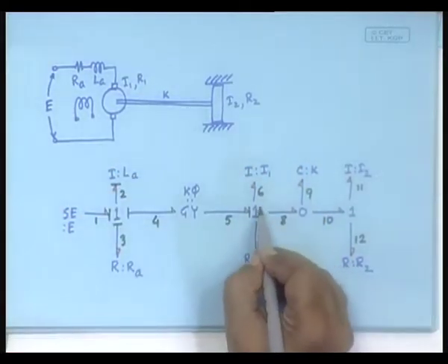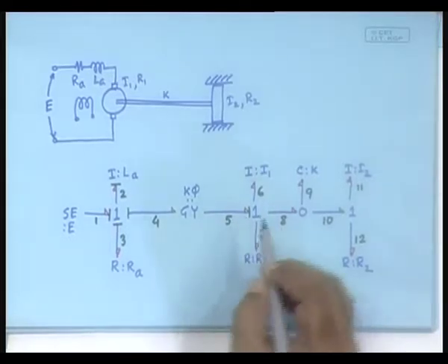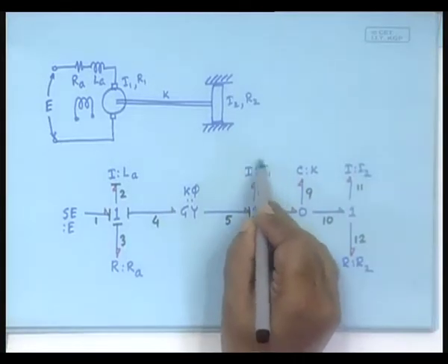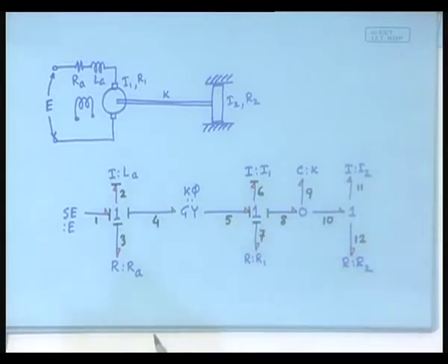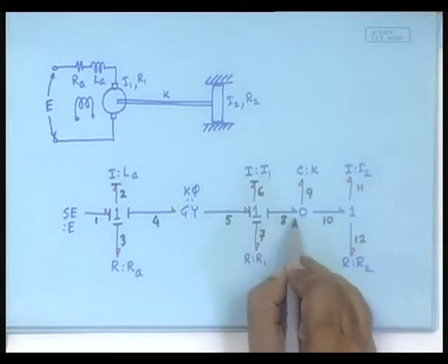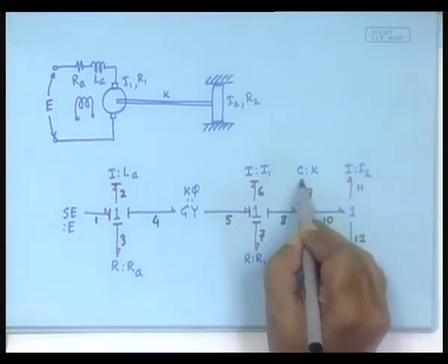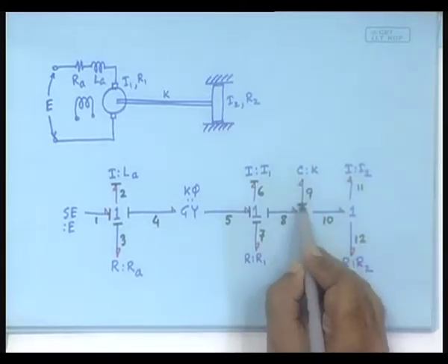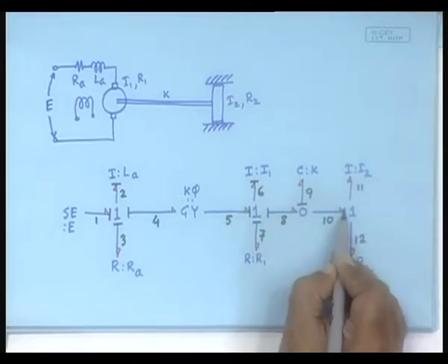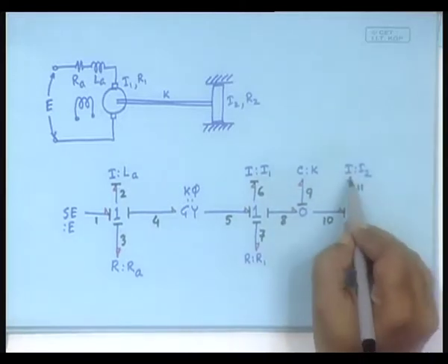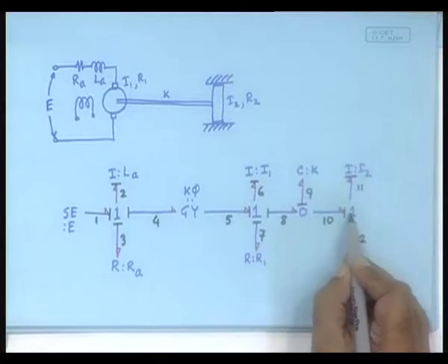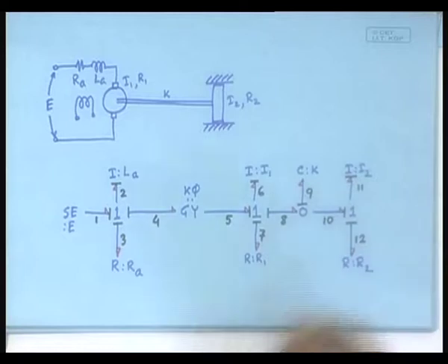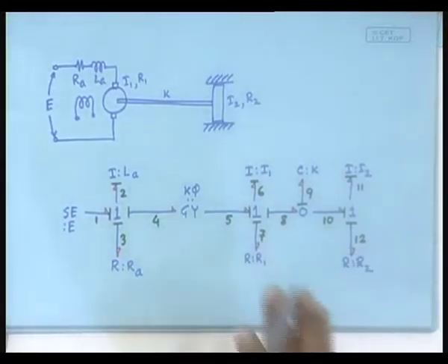So, effort goes out. Now, this one is not yet completely causal, because this is not a strong bond. So, we have to put the integral causality in this storage element, which is like this. The moment you do this, it has already obtained the flow information and must take out the flow information in the other bonds, which is right. Next you come here, this is not yet causal, so let us put it here. This is the integral causality for the C element, and the moment this receives the effort information, it must give out the effort information in the other two bonds like this. At the one junction, if you put the integral causality like this, it has received the flow information and therefore it must take out the flow information. It is already taking out the flow information here and it must take out the flow information like this. So, this is how you causal it. It has been power directed, numbered, causal, done.